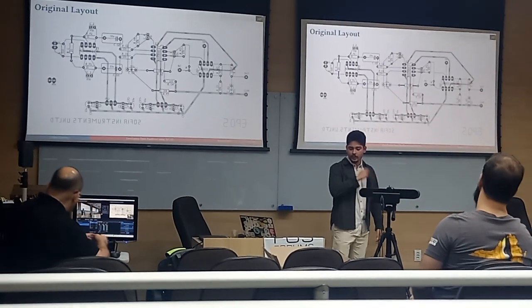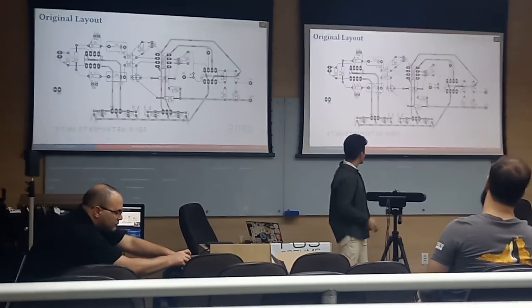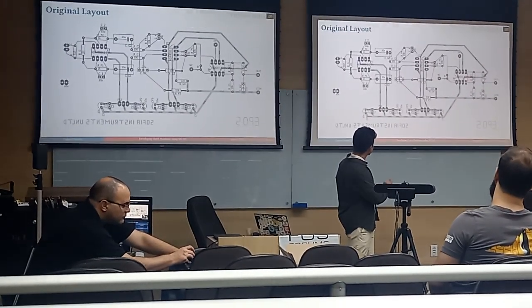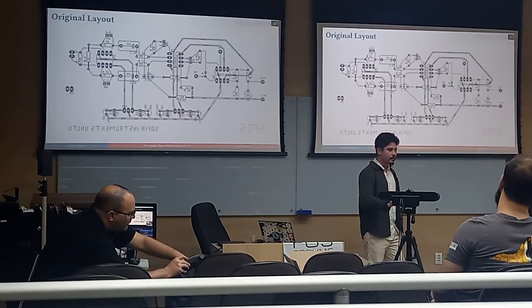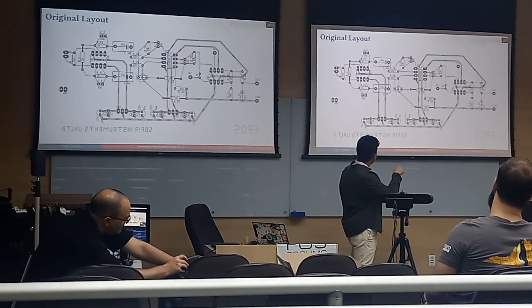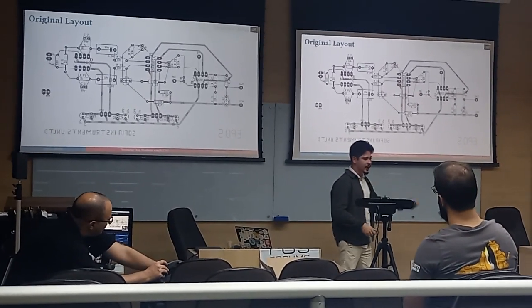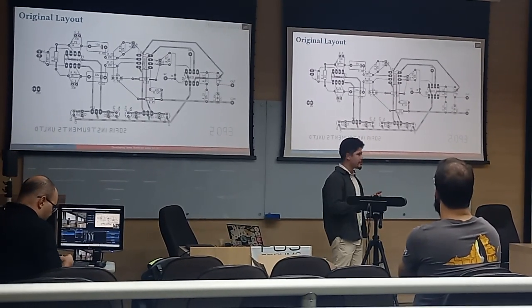This was the original layout proposed by the people from Sofia University. My idea was to replicate this. For this, just to explain, the mean square voltage value is actually in nanovolts. It's quite small. This step here just amplifies this by 1,000,000 times, so we get from nanovolts to millivolts, a measurable value.